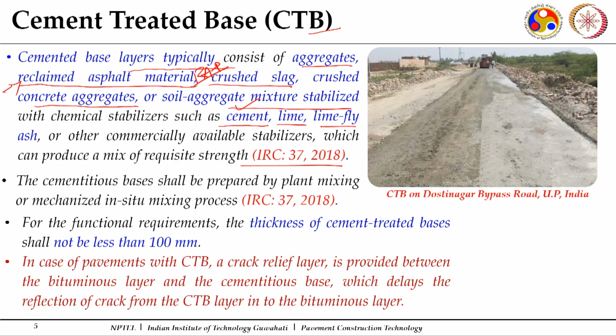Now, the important aspect is that the material which is to be used as a base course should either be prepared by plant mixing, so there should be a wet mix plant if I am using wet mix macadam, the unbound course, so it should be plant produced, or by a mechanized in situ mixing process. That should be mechanized, so as to achieve controlled characteristics. Another requirement says that the minimum layer thickness in case of cement treated base courses should be at least 100 mm.